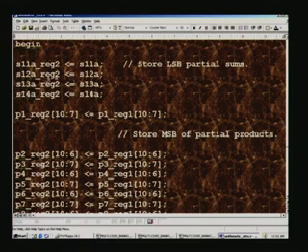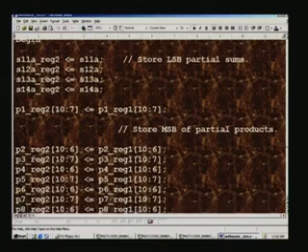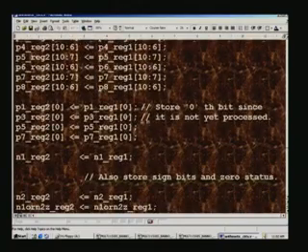This is the price that we are paying. Similarly, here we store the MSB of partial products, they are all here, P1 through P8, and this is the MSB here. Note that we have used 6 through 1 there, and we have not yet used 0, and we are now processing the MSB here, and what we are doing is merely registering this in order to process. So, here also you can store the 0th bit since it is not yet processed. We have seen that we have not added the 0th bit, but we have to register that also, otherwise that will be lost, and we are going to process it later on, and similarly the sign also will have to be propagated.